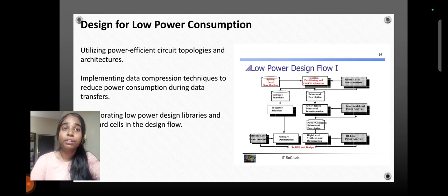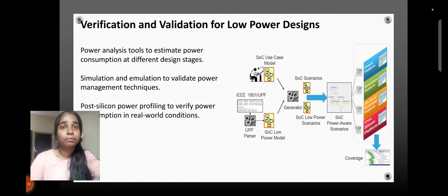Design for low power consumption involves utilizing power efficient circuit topologies and architectures, implementing data compression techniques to reduce power consumption during data transfer, and incorporating low power design libraries and standard cells in the design flow. The low power design flow has the system level specification, fabrication, and also system level power analysis. Based on the flow chart, we design the low power design flow.